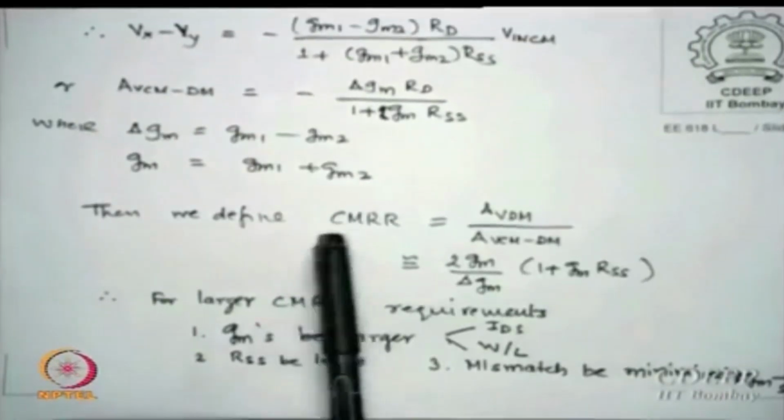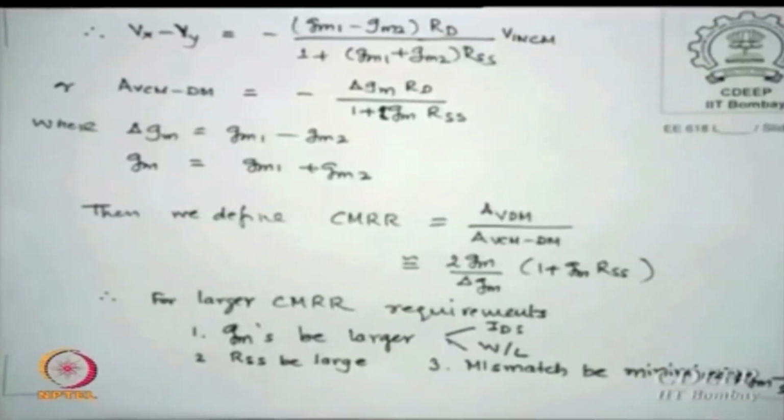So if I want larger CMRR, what is typically the CMRR in dB for op amps which you use in the lab, like the 741? The 741 has at best 80 dB kind. Normally a good op amp we would prefer is 120 dB. But if you have to design a 120 dB op amp, it will create hell of a problem for other parameters, particularly the phase margin.